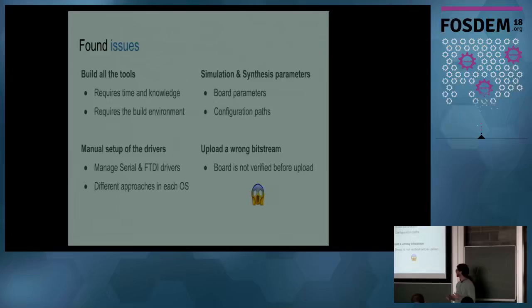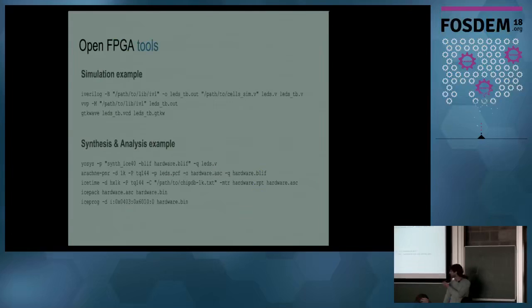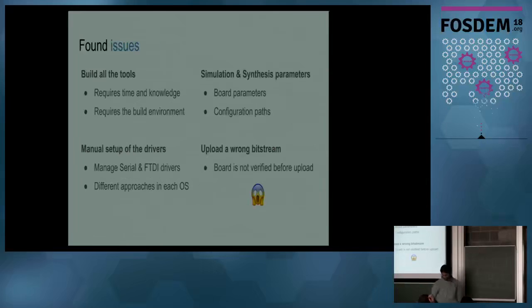There are also a lot of parameters for simulation and synthesis tools, like you saw before. For example, this is for the FPGA parameters, and a lot of paths and things like that. And you can upload the generated bitstream. That is a little dangerous, because the board is not verified.